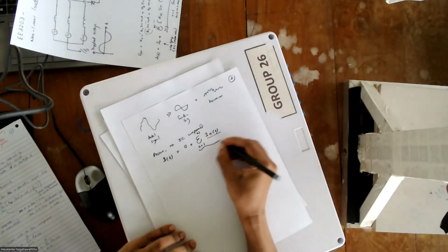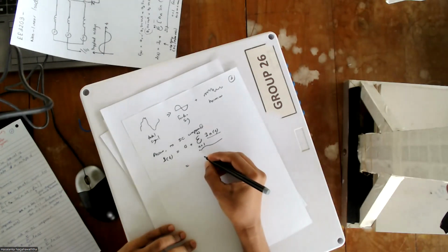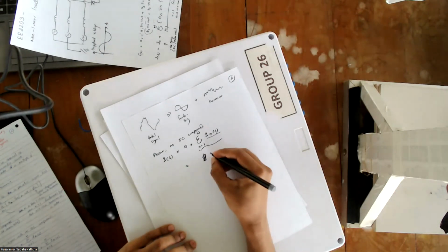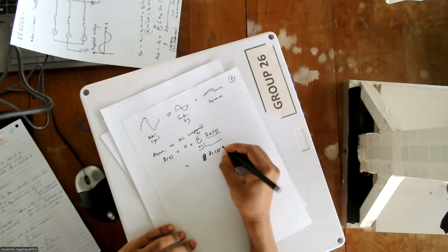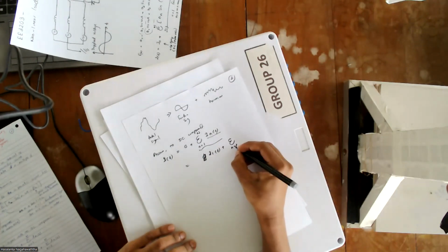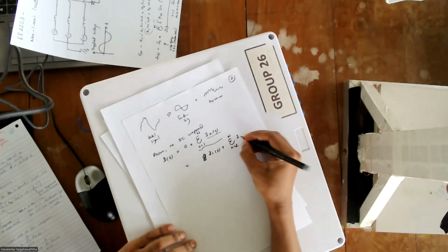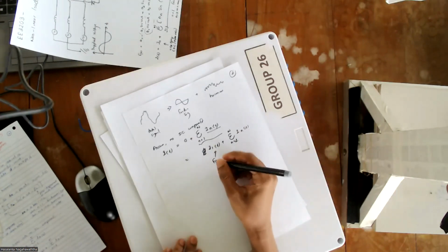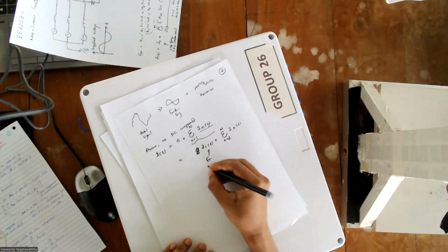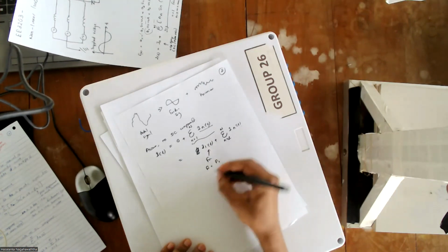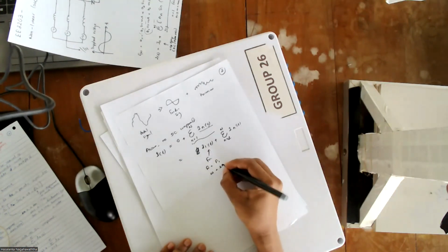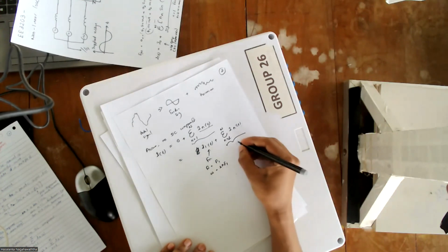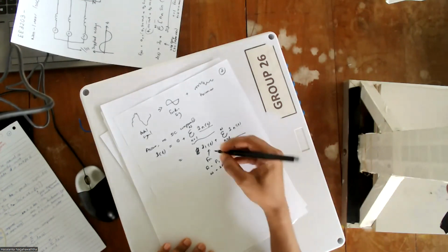Again I will separate this one: I1t plus the remaining, n equal to 2 to capital N, I n t. This is the fundamental. The frequency of the signal is f1 and omega equals 2 pi f1. These are the harmonics and remaining things.